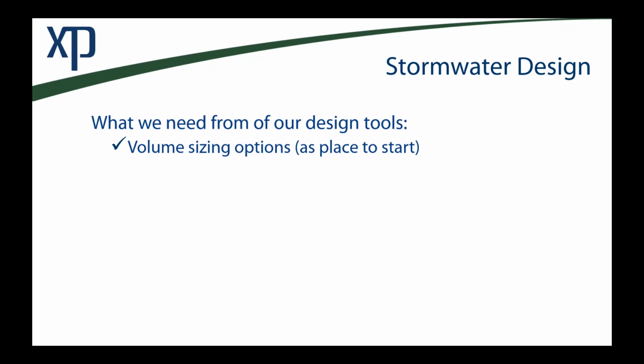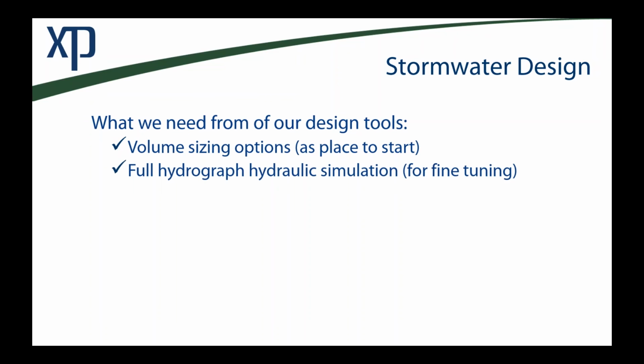So that's really the volume sizing, having an intelligent first starting point on a project. So give it an initial smart guess, and then begin to analyze that with full hydrograph hydraulic simulation. So that's for the fine-tuning, the balancing of all the timing, the outflows, depending on your design constraints.